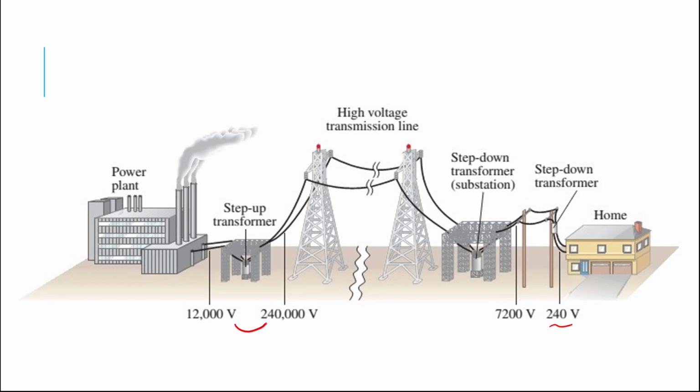Well, think about this. I'm increasing the voltage by a factor of 20. The heat loss then decreases by a factor of 20 squared. 400 times less energy is wasted by being able to do this. A huge deal. If I was trying to do this with DC power, I can't do the same step up because there's no flux change happening. So you can save yourself 400 times the heat loss by doing this step up.